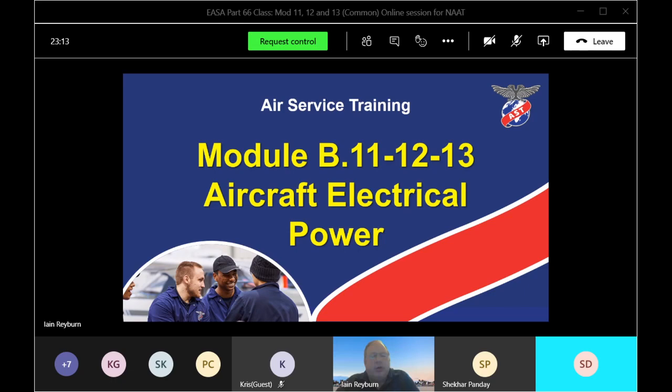Now, we're talking electronics. Electronics, with a whole lot of transistors, is on or off. So here I'm going to have, it could be, 28 volts DC as my excitation voltage. Other aircraft might be slightly different. But that 28 volts will be there all the time. So I can't increase the excitation voltage up to 30, 32 volts, and I can't decrease it to 24, 22 volts. So what can I do?